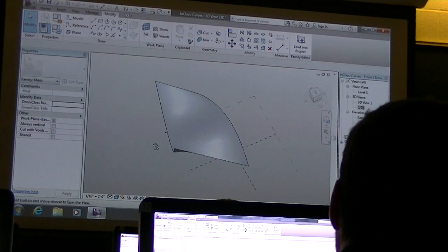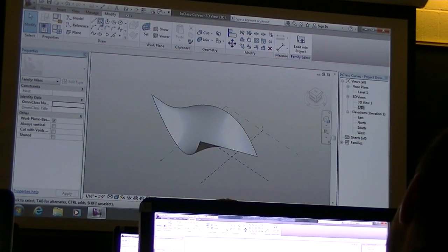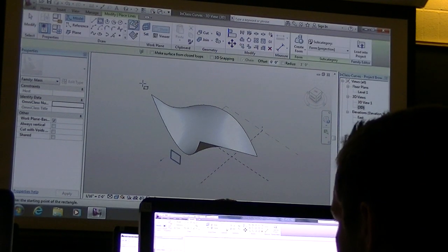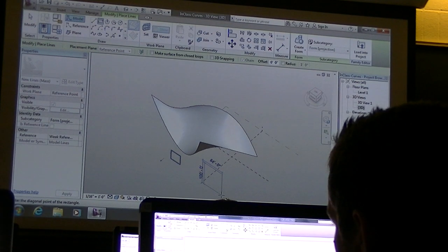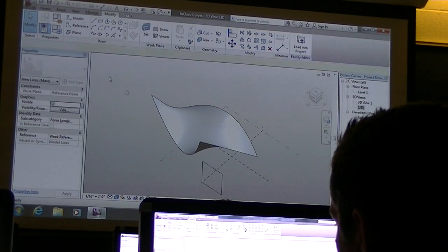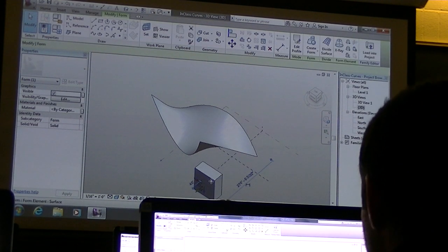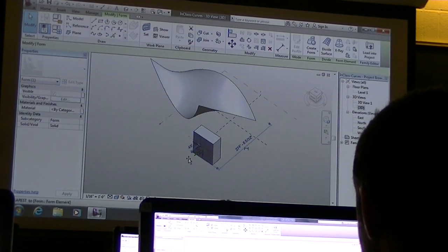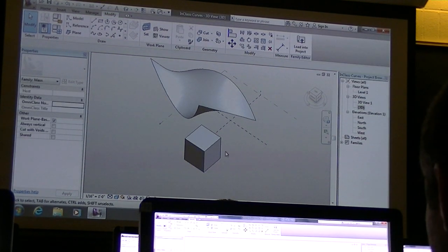So just real quick, Revit essentially, and you probably have done this in Vasari. In Vasari, I could draw a rectangle, and if you hit create form, it creates a box, and it makes this extrusion that you can move up and down and so on.